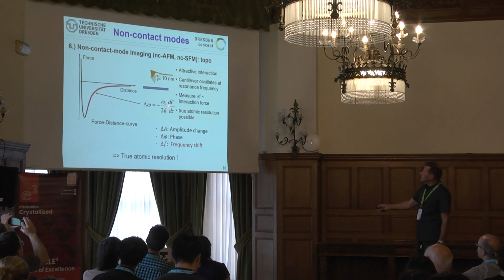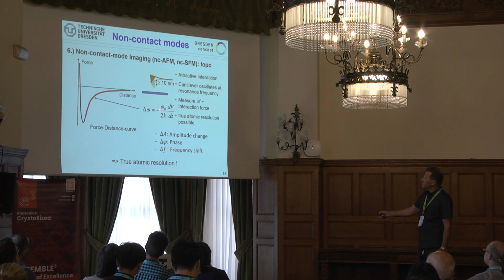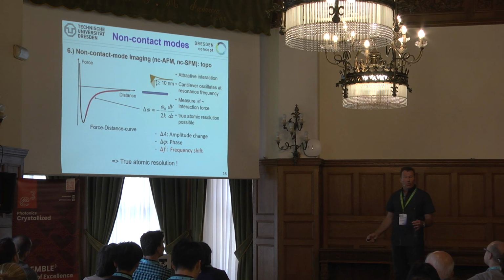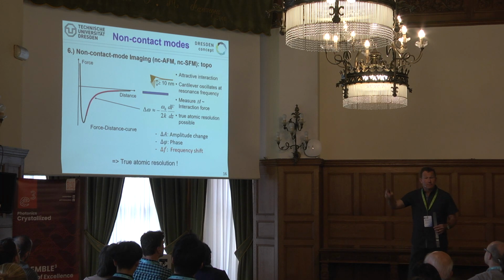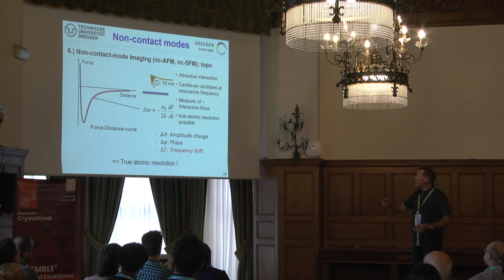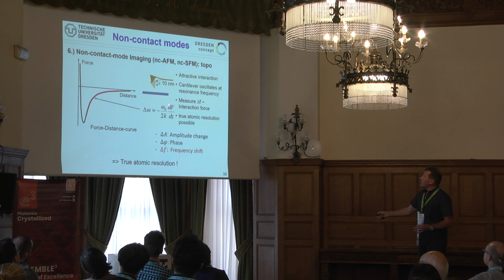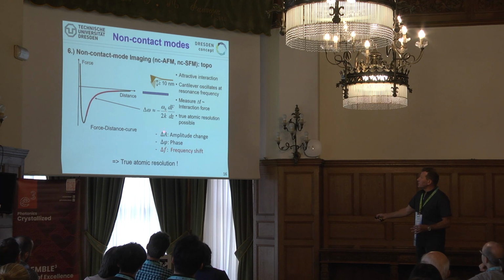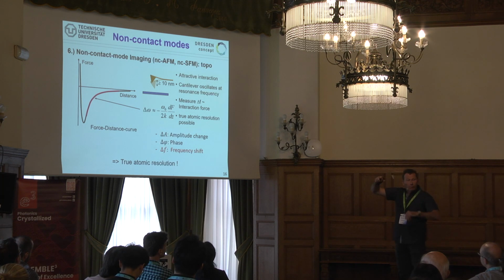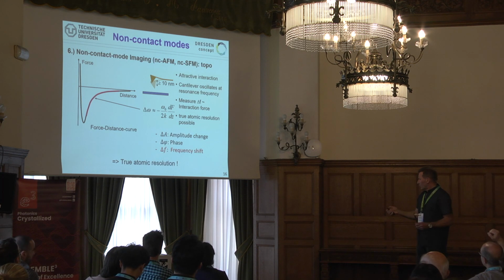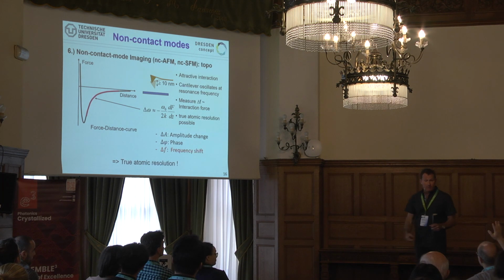So we are vibrating the cantilever at its resonance frequency, omega 0, and by vibrating I'm no longer sensitive to the force, but rather to the force derivative, because we're changing that and we're integrating over that one, which means we have now a couple of things to look at. We can look at the phase. That's actually what everybody does so far. But we can also look at the amplitude that really gets smaller once we get closer. Or we can also look actually at the frequency.